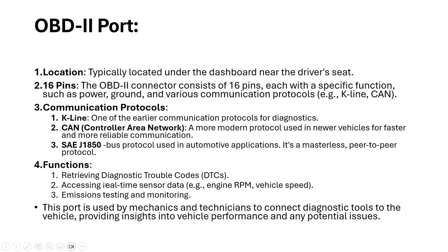The functionality of this port is that it is used to retrieve the diagnostic trouble codes for the purpose of diagnostics, and it's also used to access real-time sensor data like engine RPM, vehicle speed, emission level, etc. And also it is used for emission testing purposes.